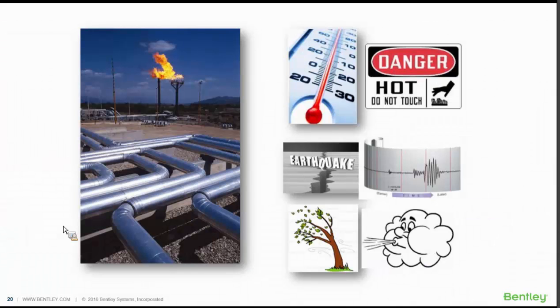Soft and hard clashes between vessels, piping, whether it be insulated or non-insulated piping, structural, electrical, equipment, etc., can all occur, and it's important to investigate them. Clashes are typically caused by pipes heating up and moving, but large pipe movements can also easily occur with extreme loads, such as wind loads and earthquake loads.